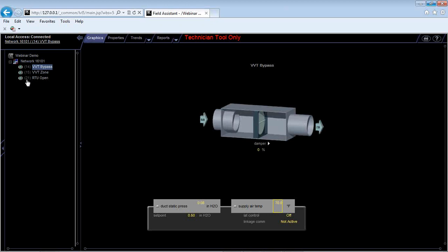And then it actually sends data back to the master stat, like what its supplier temperature sensor is, what mode it's in, and a few other parameters. And from there, the master stat sends all that information out to the slave. This is all auto-generated logic that's built into all of Carrier controllers. It's just a matter of setting it up to function and confirming that it does function, which we're going to do today.